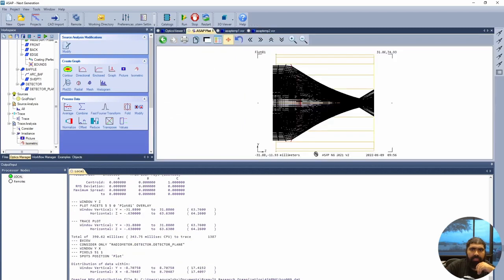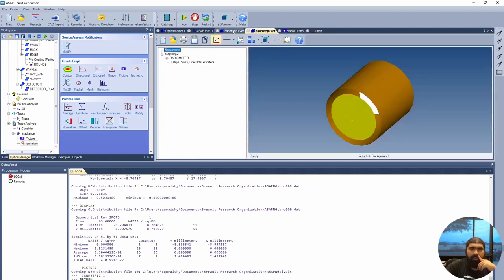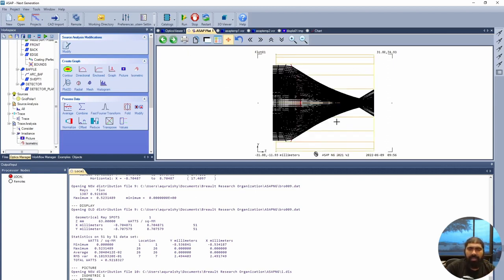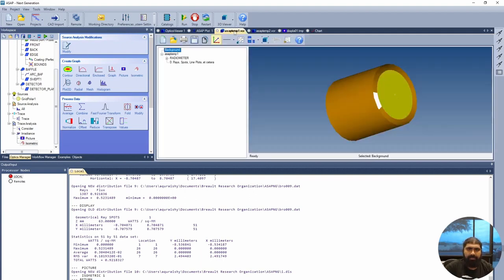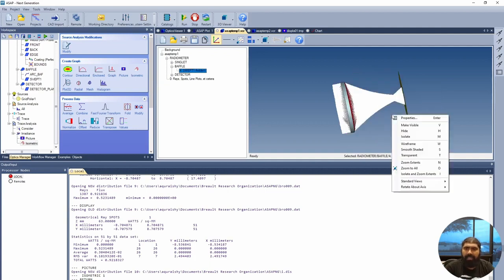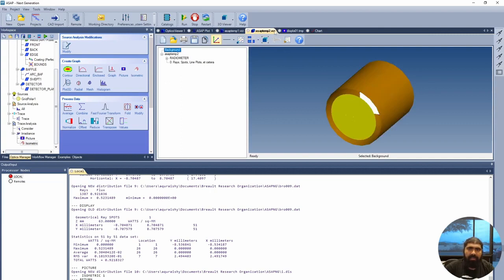So we reproduce again the system, the 2D viewer, and from here you also saw that within the plot we also got an XY view. If you want to see the other view, you would press the back button and you're able to see the rays from this surface as well as the surface of the detector. And that's where you see these concentric lines from. Once again, and also before I made it transparent, let's actually hide it entirely. So let's press the hide button and you'll see how the light goes through the lens and how it hits the detector. And we can see here that it created a second one.